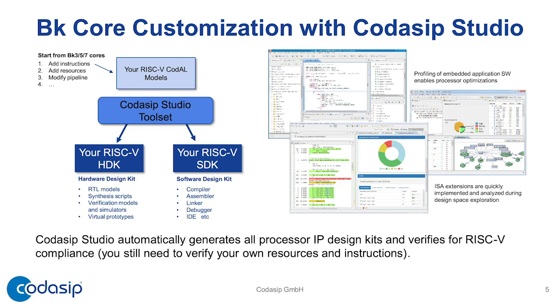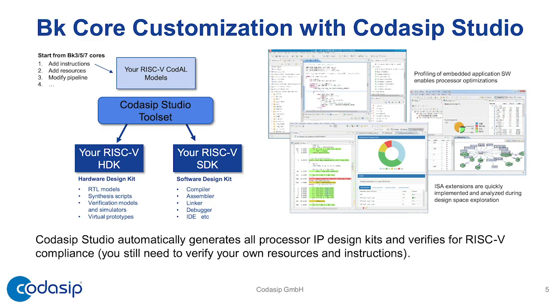And then you also have an SDK that is aware of the extensions that you did in CodAL. The SDK itself is LLVM based. Currently we are based on LLVM 8, I think, at the moment. We are also using a debugger from the LLVM project, so LLDB is there as well. We have a couple of C libraries, newlib for instance, or other libraries that you need for the C or C++ runtime. All the low-level programming tools, assembler, linker, disassembler, are available there as well.